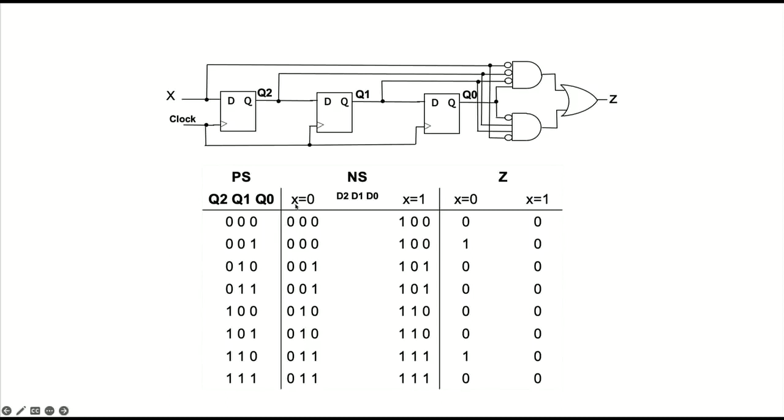And so the next state, well, X will become the first bit of the next state, and then we will lose Q0. Right? Because all we're doing is we're shifting in X and we're forgetting Q0. Q0 falls off the end. So you can see all these next states start with 0, and all these next states start with 1. And basically, we just shifted this over. Okay? So it was easy to fill in a table because this is a shift register.